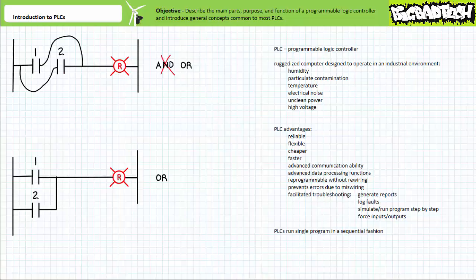In addition to these advantages, PLCs are designed to facilitate troubleshooting with diagnostic tools. Depending upon the degree of complexity, PLCs can generate reports, log faults, and technicians can simulate and run the program line by line or force inputs and outputs.